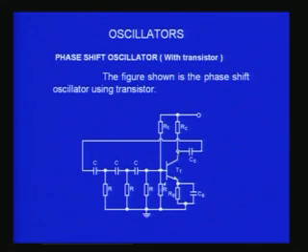Now what are we doing? We are taking the output, and you see it is brought back through this wire to the input, and at the input, you keep on combining a series of RC sets. That output is taken and given to another CR, that output from the R is taken to another CR, and that output is given to the input.